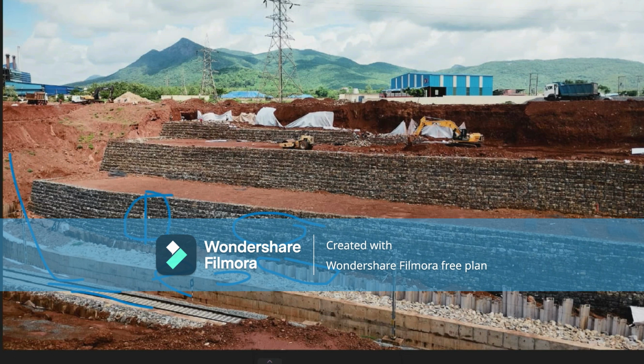Slope, and then again the same gabion box wall, a retaining wall, and then a third berm constructed here. The geotextile is provided to prevent the pore water or sand material from entering this fill, the existing soil from the first construction, and the nearby hill above, so that's why the groundwater level is also high, 1.5 meter, which is quite okay.